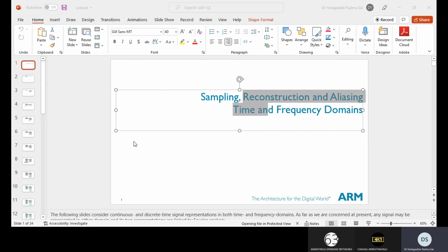So these are some of the things generally used in signals. Based on this, we classify whether a signal is continuous or discrete, periodic or aperiodic, deterministic or random, energy or power. In most cases, all periodic signals are power signals. In some cases, signals are neither power nor energy, and aperiodic signals are energy signals. In general, that is the concept.